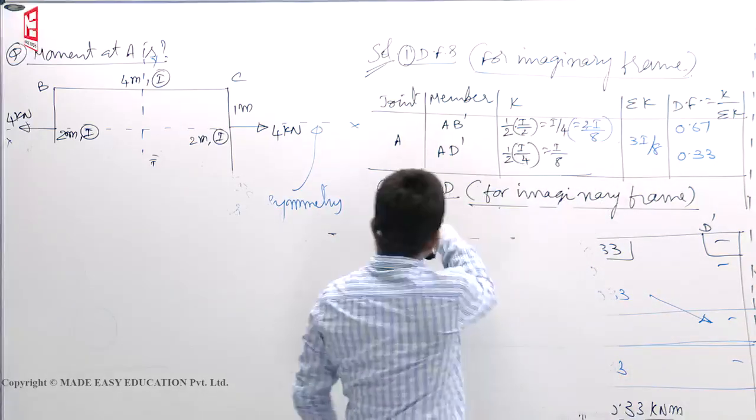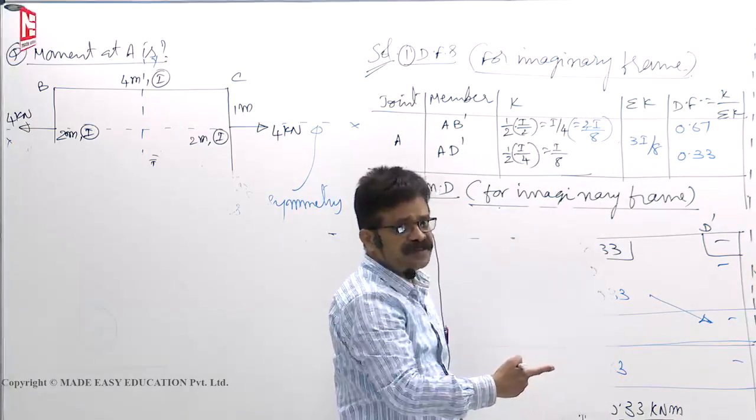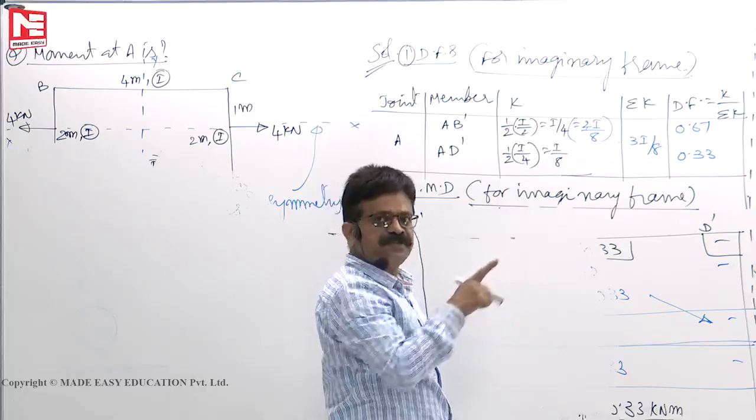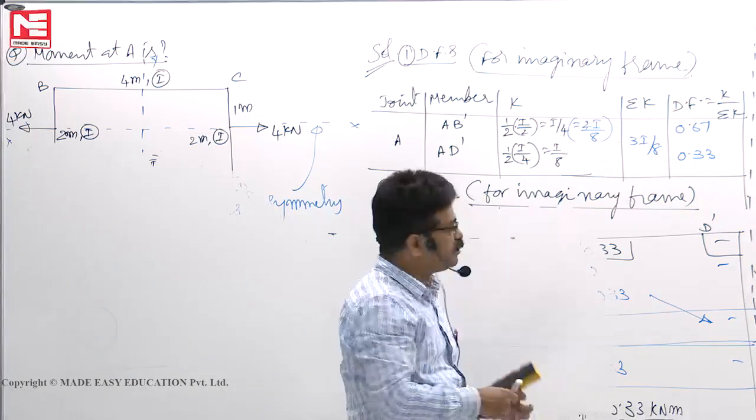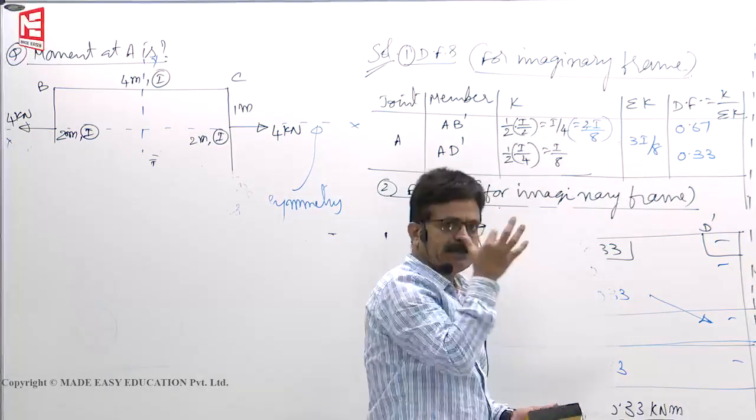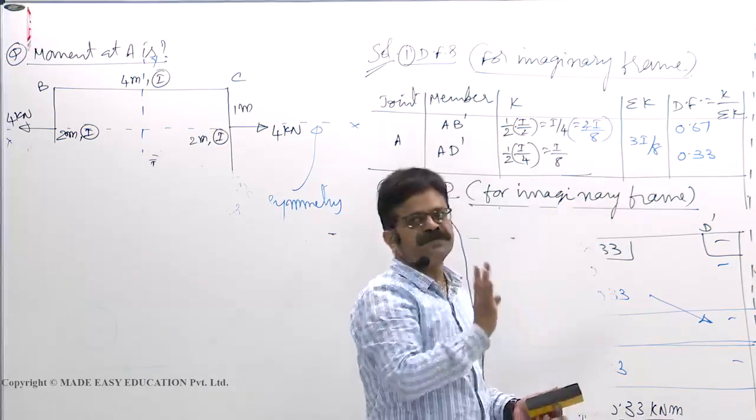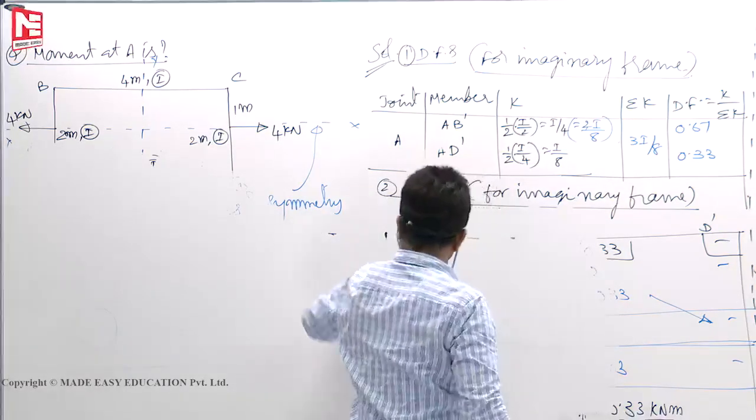In all these problems, you see fixed end moment, final end moments are different. If fixed end moment, final end moment are same, that means that all slopes are 0 after unlocking also. That is the implied meaning there.